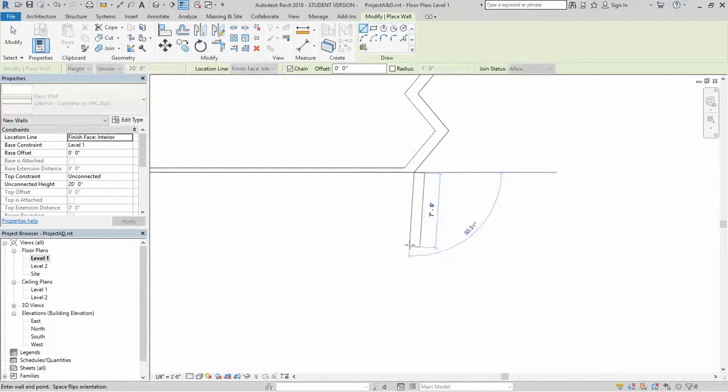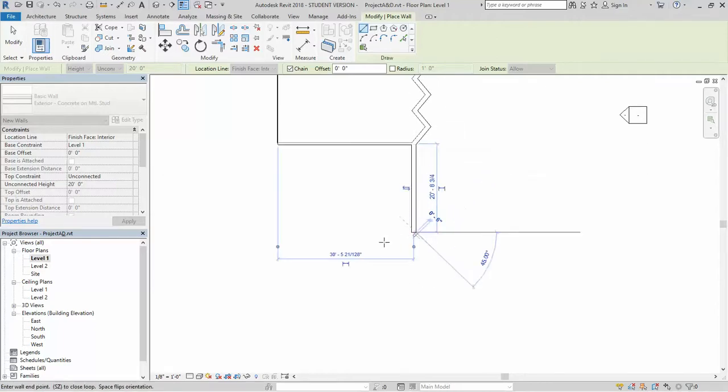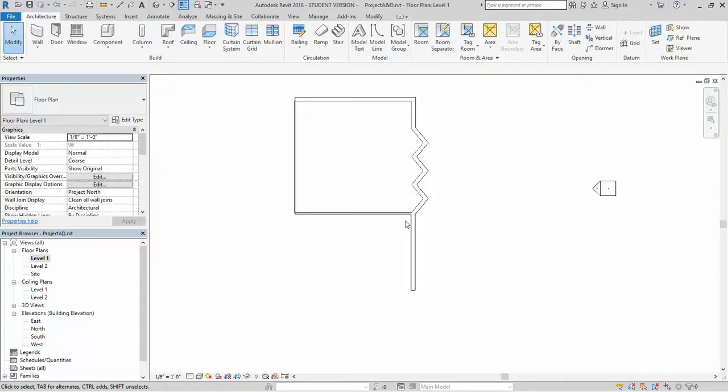If this happens to you as you create the wall by clicking once and coming down, you press spacebar and it goes towards the interior. There we go. This just simulates the rest of the building, even though it has windows. This is just good enough. I'm going to create a roof and a floor. So let's start with the floor. In order to create a floor, you need to make sure you're actually in level 1 or in the level that you want to create the floor at.